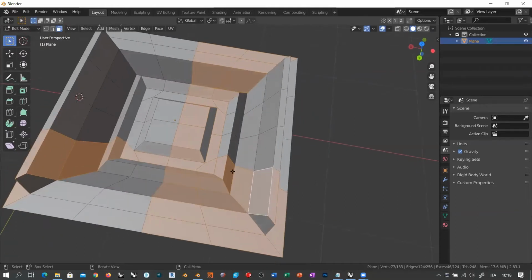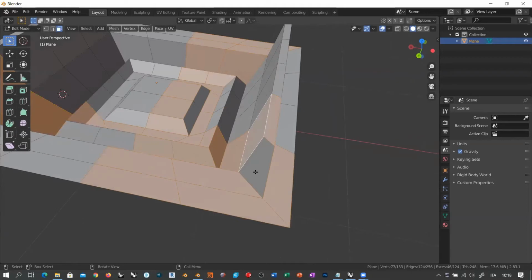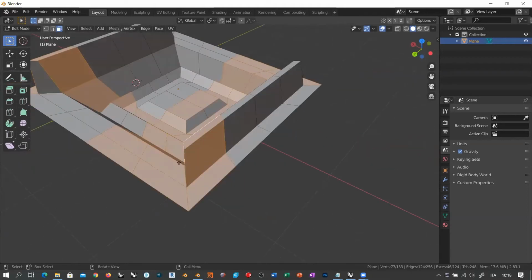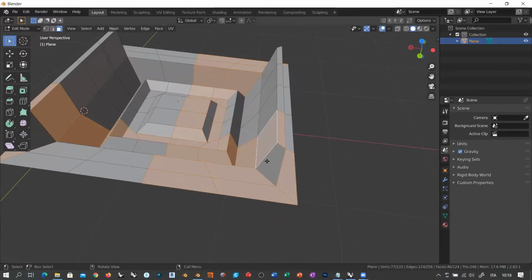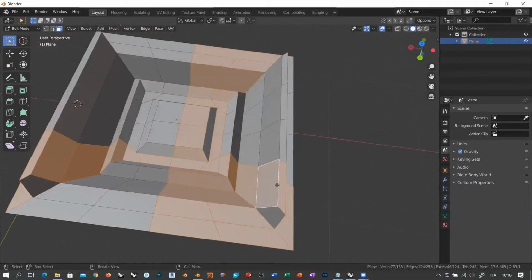And this is actually overlapping with these two loops here. So this polygon and this polygon belong at the same time to these V loops and to this U loop here. And also this selection is leaving this polygon here outside from the selection. So another polygon that stays here, disconnected from the UV theory of polygons that we have. Okay, so there are lots of problems in this mesh.